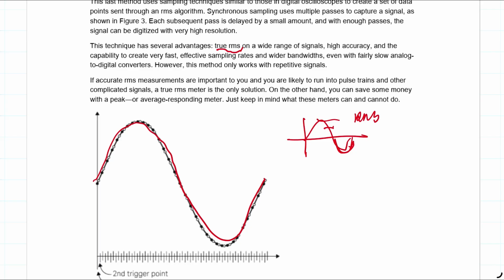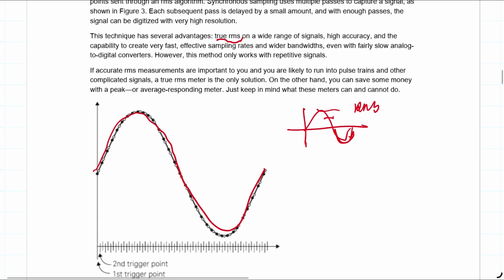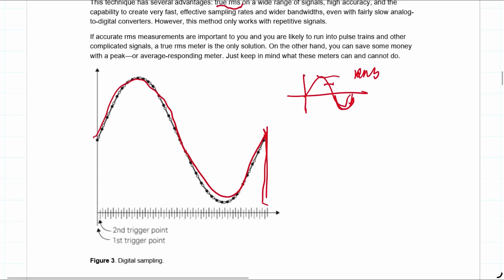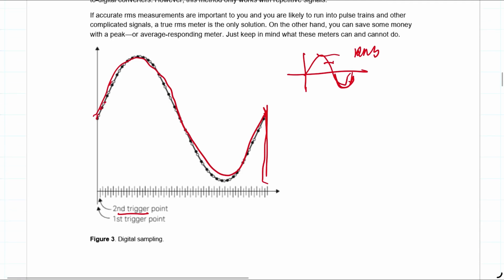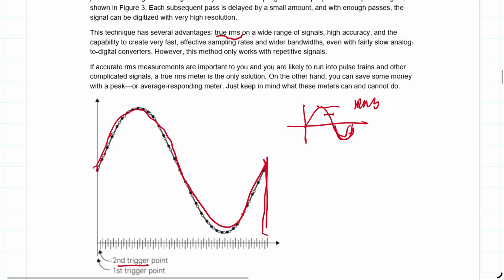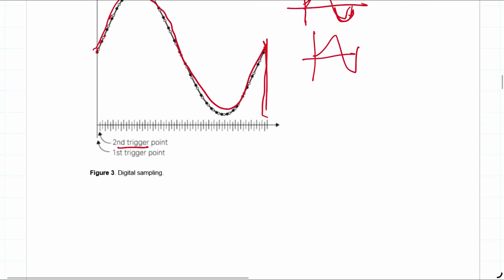Of course, the assumption here is that the signal is periodic. The signal will keep repeating itself. To improve the measurement resolution, you can also sample different periods with a little bit of offset. Equivalently, you have more samples. So this is a kind of compromise between price and implementation. You can use this to measure not only a sine wave, but also a triangular wave, for example. So this is very popular.